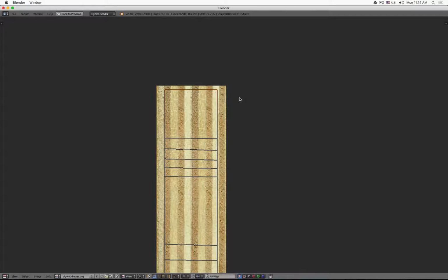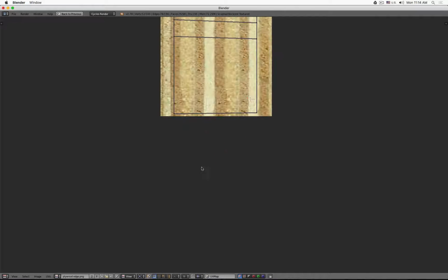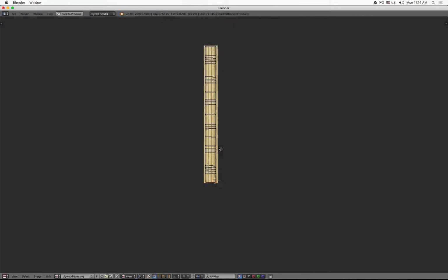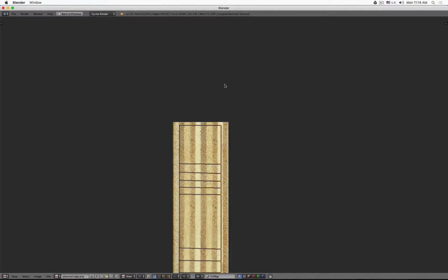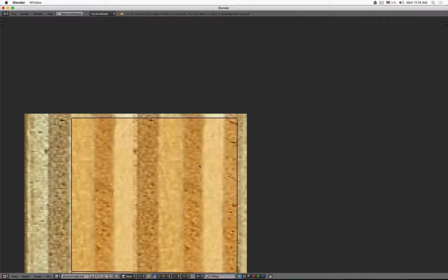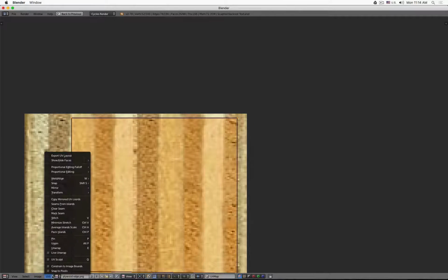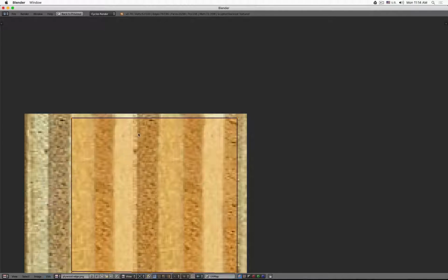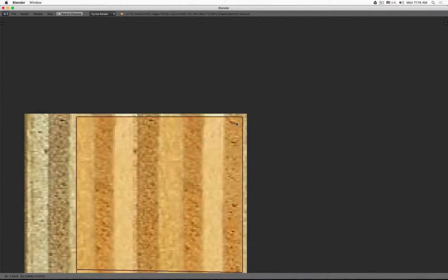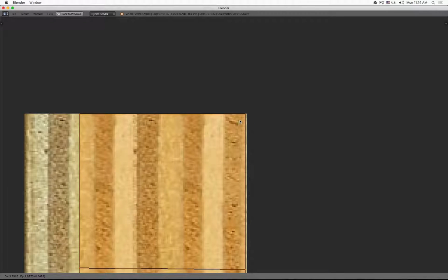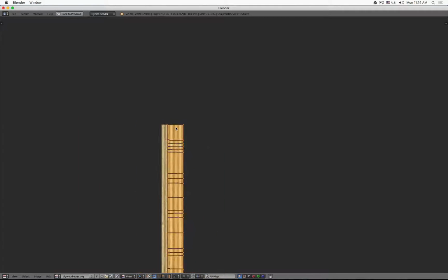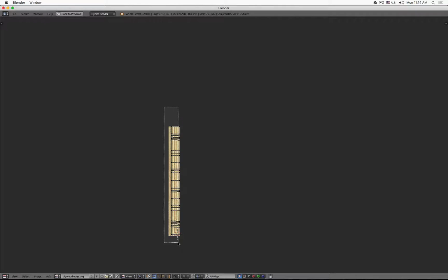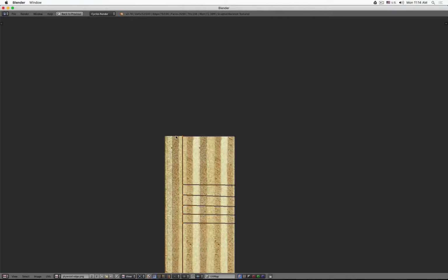Here, S and Y, at the bottom, S and Y. Okay, and now I will try to maximize the amount of pixels. So I could go to snap to pixels in UVs. And with everything selected, when I press G now, you see it snaps in there. The upper right corner and upper edge is aligned.